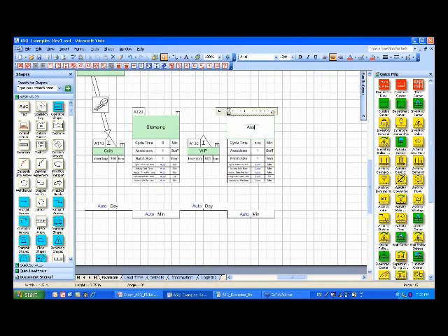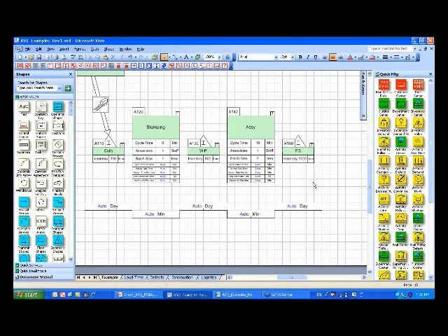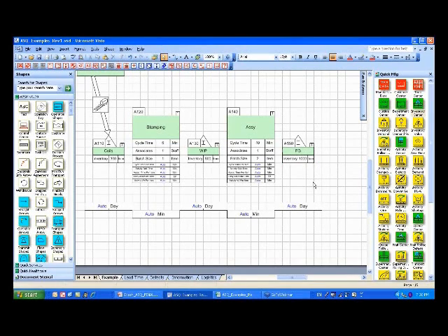And let's say there's only one more step, which is assembly. The cycle time here might be 10 minutes, but every 10 minutes it's producing 2 parts, so I'm going to give it a batch size of 2. And for our simple map, let's say that finish creates my finished goods. I'm going to call it FG for finished goods. When they do the measurement, they walk the floor. Let's say they happen to see 1,000 parts sitting here. To some extent, the value stream map is a steady state map. So it's best to measure these numbers when you're in some kind of steady state, not when you're going through rapid growth or a rapid decline in production, because you'll get false numbers for these inventory numbers.